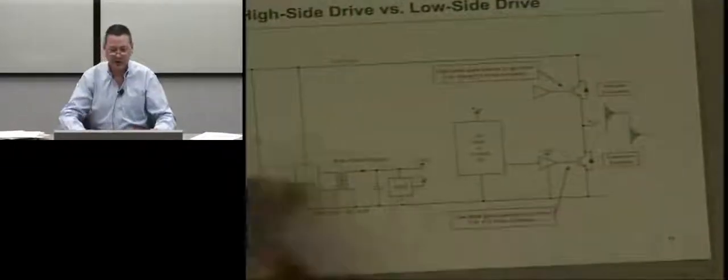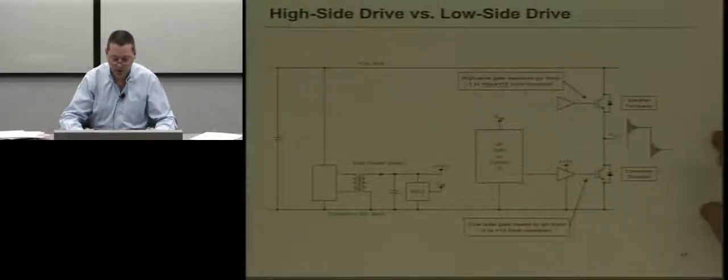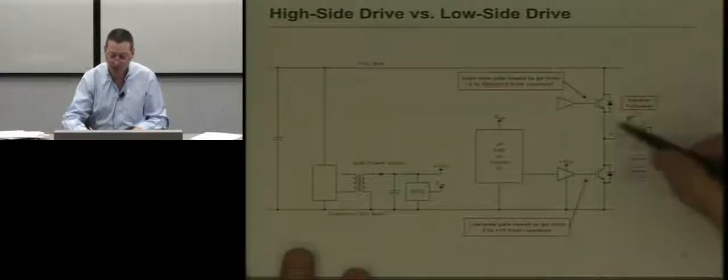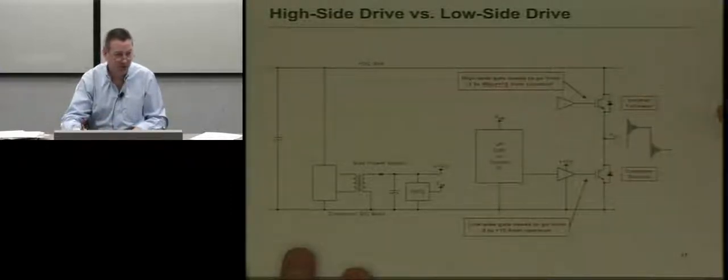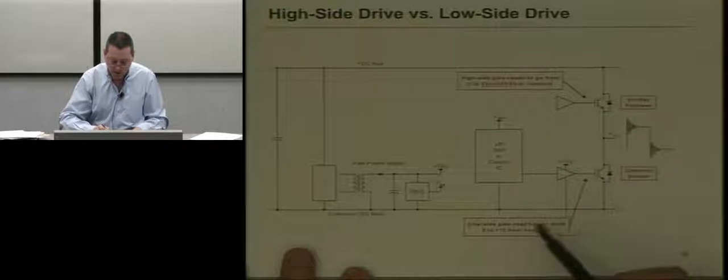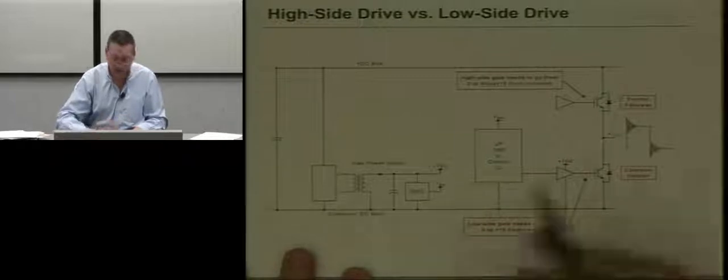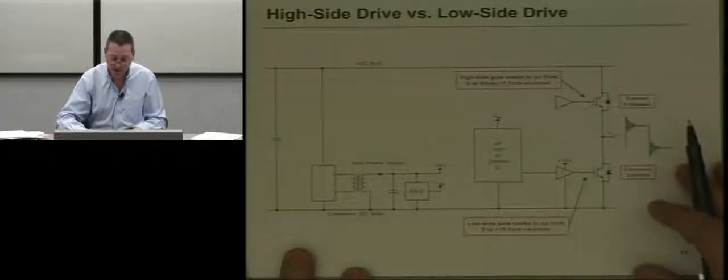Quickly talk about gate drive. The goal in gate drive, and again, we're talking most commonly about the half-bridge topology, which is used for UPS, motor drive, any kind of inverters. And there's different ways to do this. One of them is, and I'll show you in a minute, complete galvanic isolation.